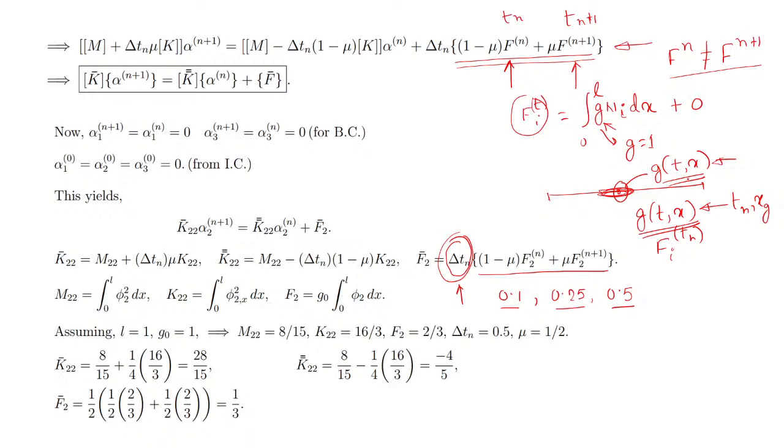Why? Because this is just to show you that the choice of time step actually decides your approximate solution. If you remember, in the case of a steady problem we said that when you get a solution at the end of the running of the code, you are getting basically an approximate solution, and you should always check for mesh convergence.